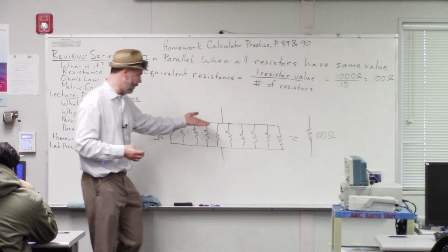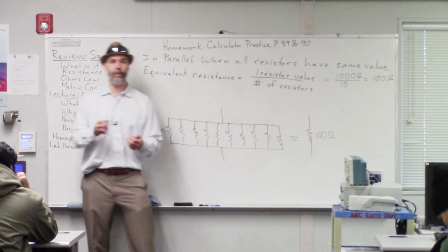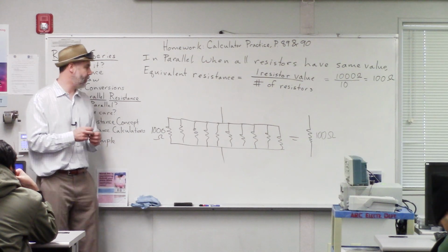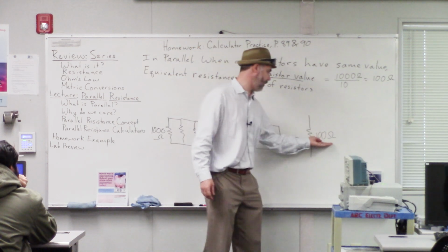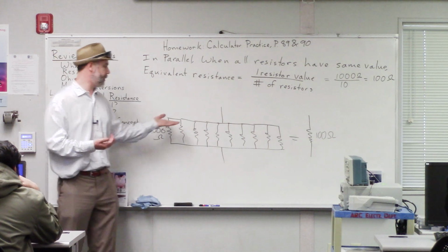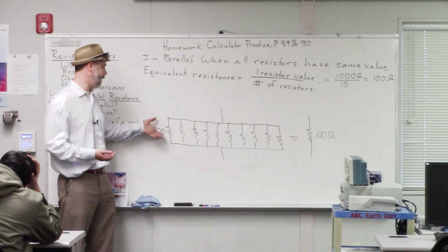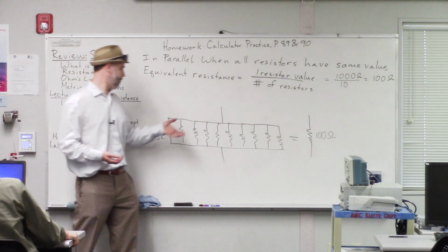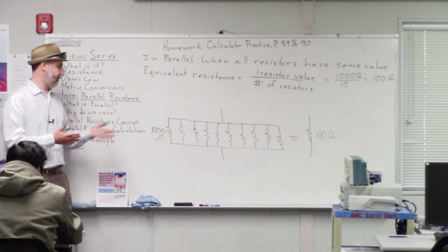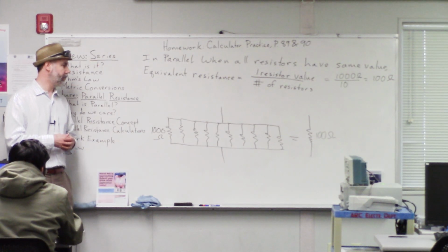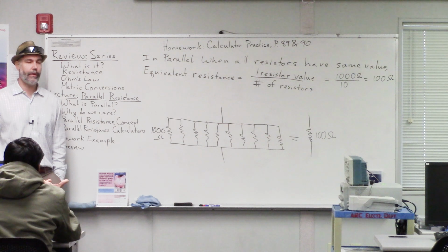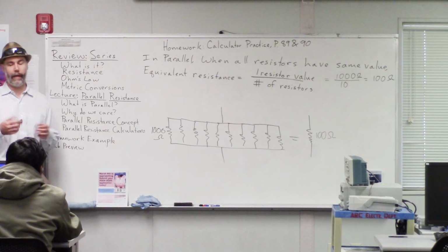And they needed to use parallel circuit math because they knew that dummy load had to have a resistance of 50 ohms. And so they wanted to have a final resistance of 50 ohms. And so if they knew they wanted to use 10 resistors, then each one would be 500 ohms, because 500 divided by 10 would give you 50. Okay? So this is something that could be used in the real world. Okay? And resistance changes when it heats up. When they heat up? Yeah, it can a little bit.